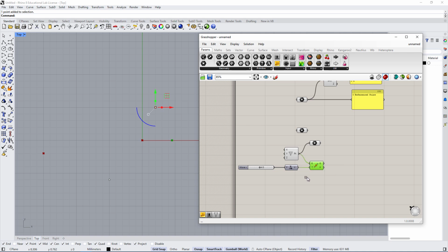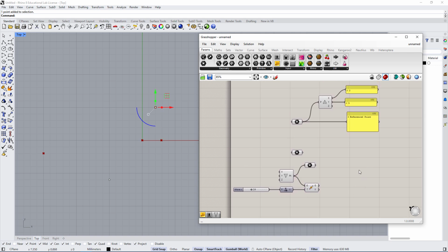Now in this case, if you want to move an object, you can still move it, but you have to use a translation and you have to define the input for the translation. What that does as well is it allows it to be very dynamic, because if you want to make a change here, you can change it and anything that follows will also change. But in Rhino, if you move a point, depending on what you're doing, it may not update all of the rest of the geometry. So hopefully this makes sense, and this gives you a better sense of how you use inputs to create geometry or to create your definition.